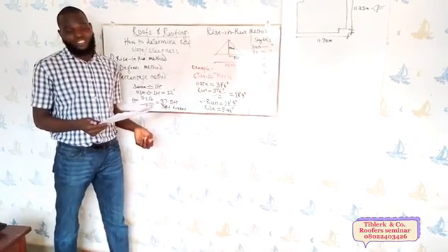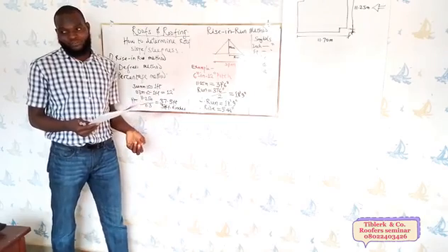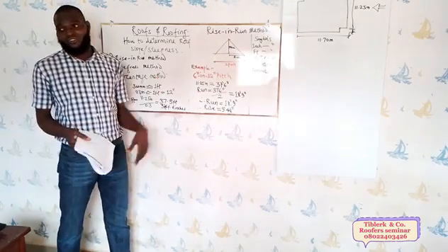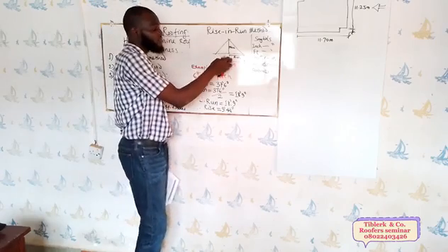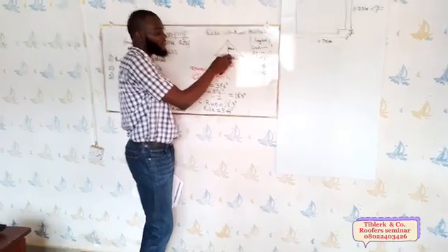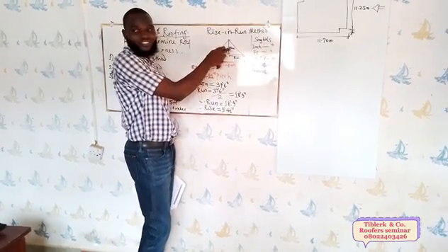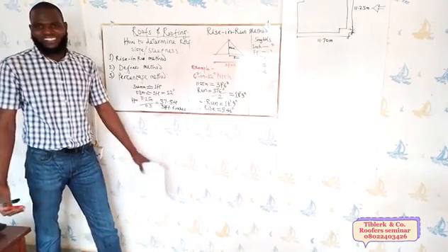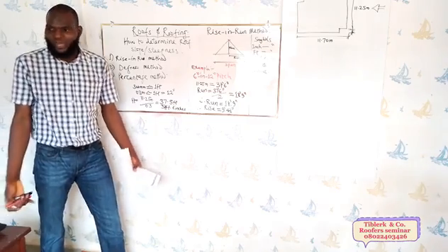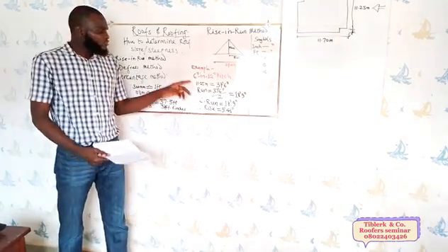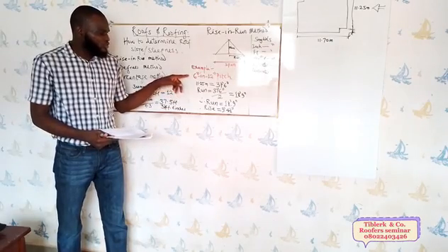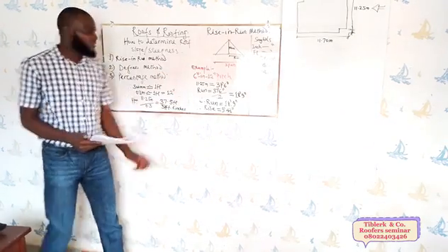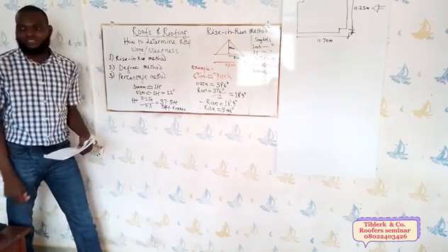For instance, let's assume you are given a 7 in 12 pitch, 7 inches to 12. It might stress them to be calculating for every 12 inches, going 7 inches each time. So as a roofer, as a professional, you can decide to change it into degrees.